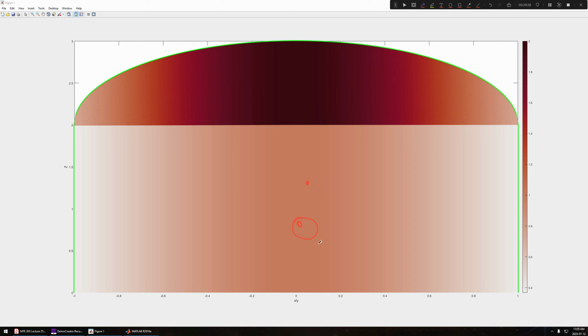I forgot its official name, right? So if the center of mass is higher than here, when I put a force this way to launch the rocket up, it balances out because the force that I push is acting on here, right? But the force from the air is acting on here. So if these are two off kilter, what'll happen is I could take my rocket and tilt it a little bit, and then it'll keep tilting further, right?